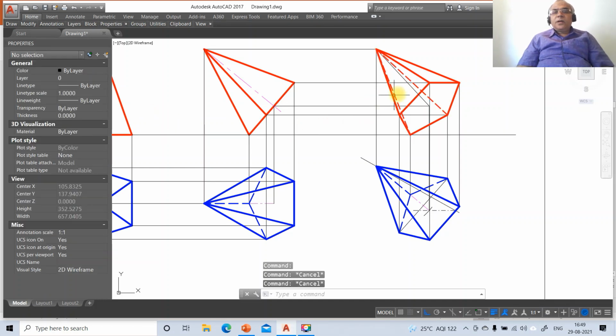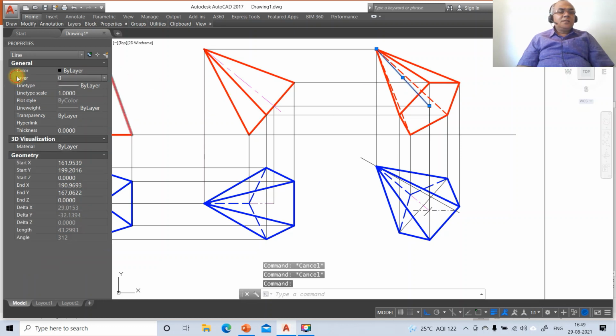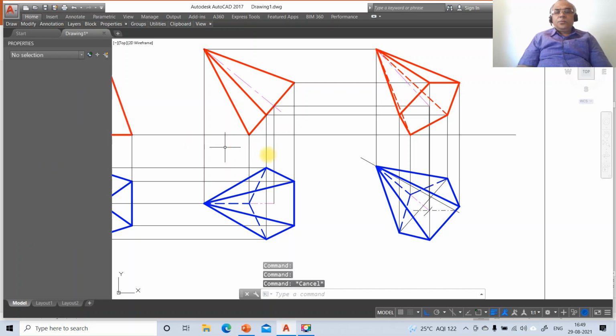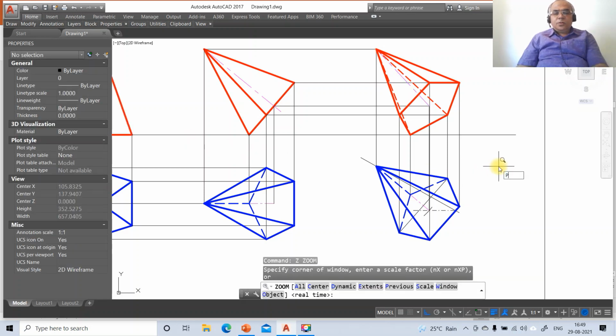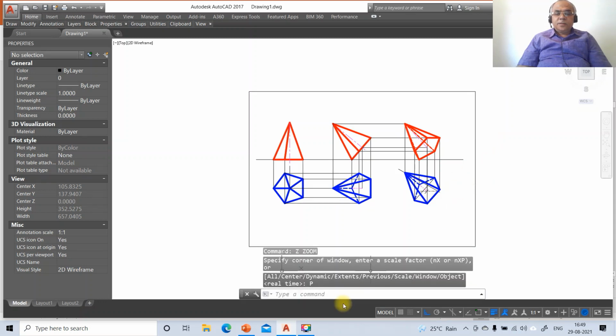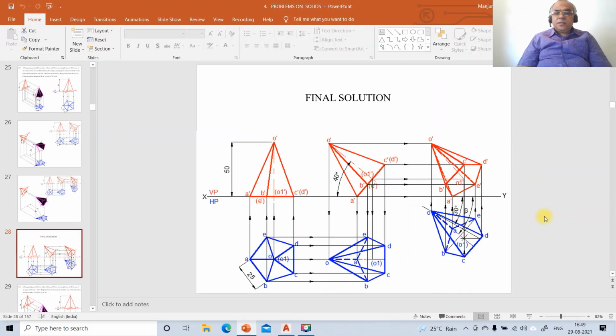Once you do that, now we have the axis line. Select this and go to this and make this as axis line and take this as 10 mm. Now we have this line. So now the entire drawing has been completed. Now we need to name them.